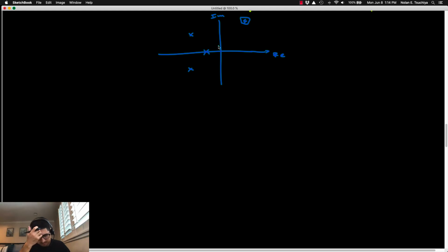Let's say I have those three poles, but I also introduce a pair of poles on the imaginary axis. So five poles total. It's a fifth order transfer function. I don't need to do anything other than consult the definition that we just derived to say that this is a marginally stable system, because I've got some poles in the left half plane and some poles on the imaginary axis, but they're not repeated. So that's marginally stable.